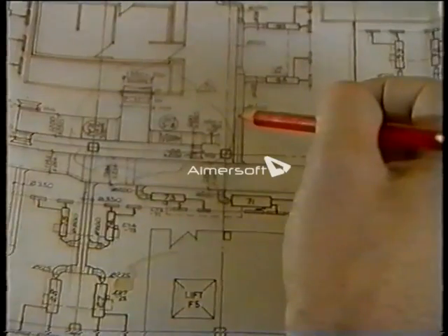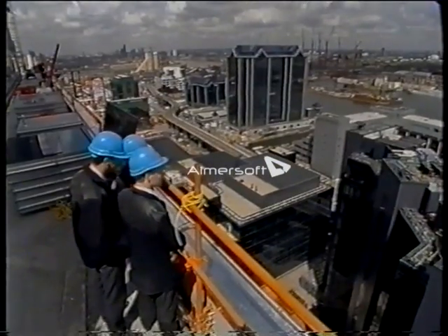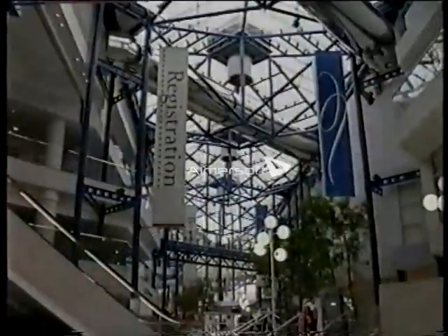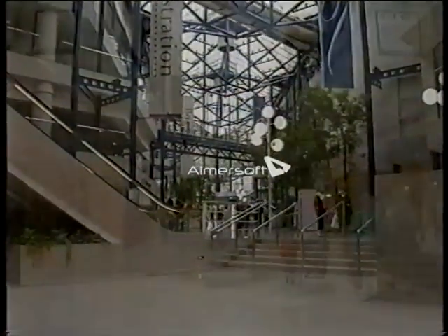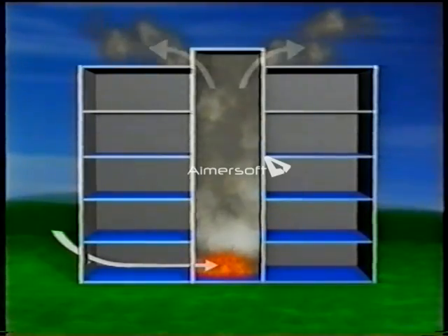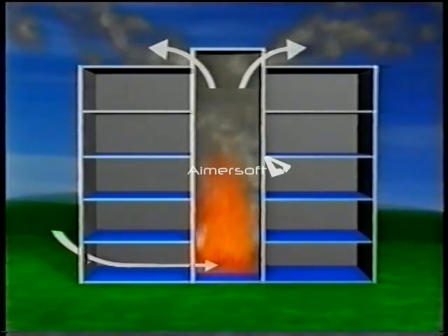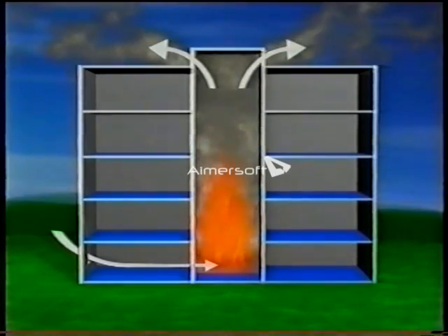The building trend in cities is towards high-rise blocks, possibly with underground car parks. Local conditions in atriums and full-height stairwells can also cause problems for firefighters. The first of these is the stack effect, where large vertical spaces inside the building act as a chimney for hot smoke and gases that are ultimately trying to find a means of escape. If there is an inlet at low level and an outlet at very high level, fast air movements can develop between the two, fanning the fire.